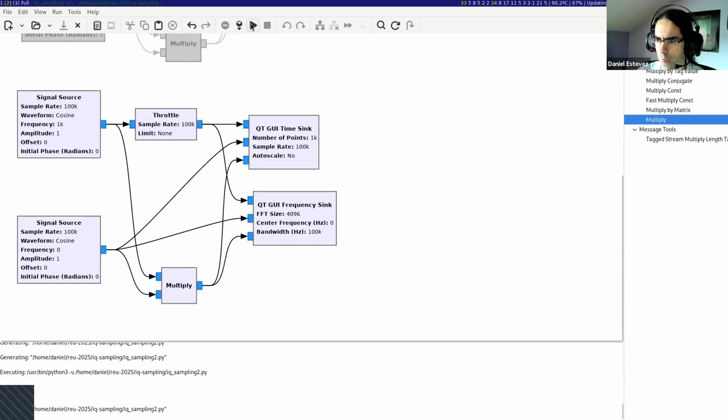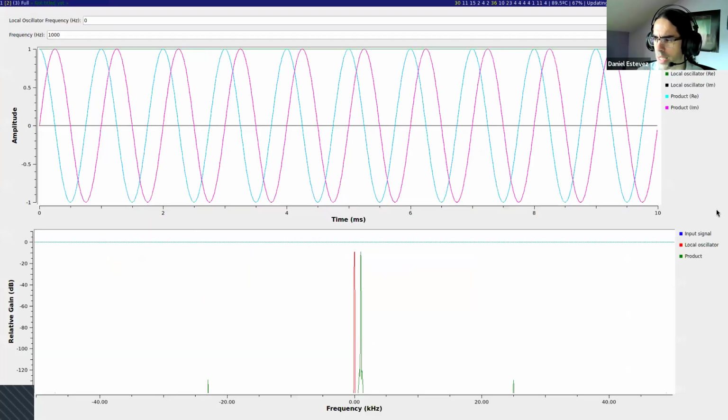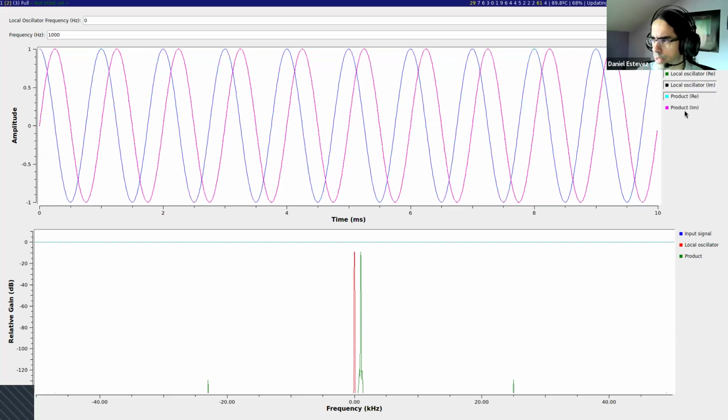And signal 6 should be the product, imaginary part. And on the FFT display, I do not have to change anything because the complex signal is used as a whole, and the FFT is computed, and we only represent the power of the FFT, which is the modulus or absolute value of the complex numbers which come out. But in the time domain, we have the real and imaginary parts separately. So I'm going to disable things to explain them step by step.